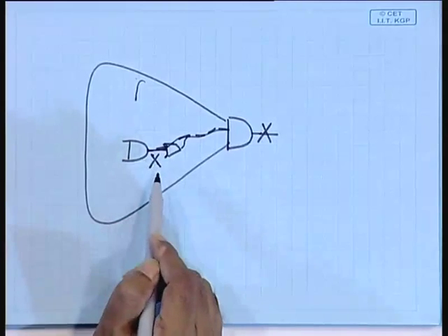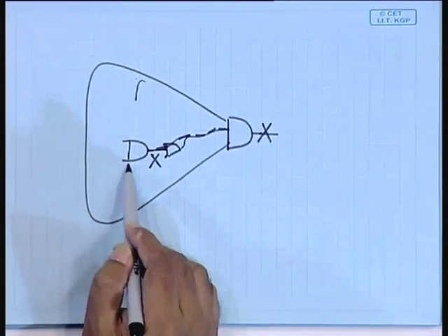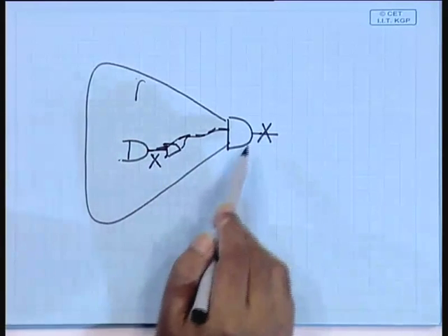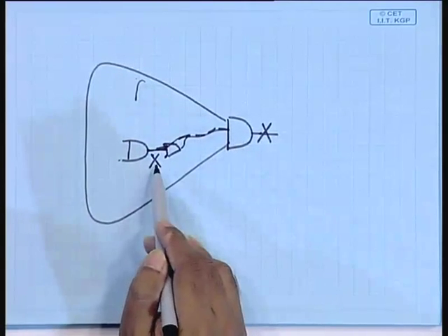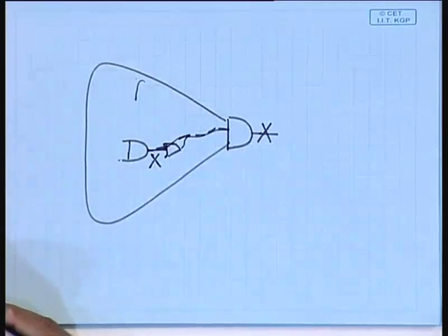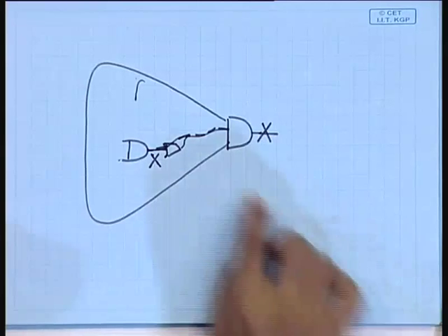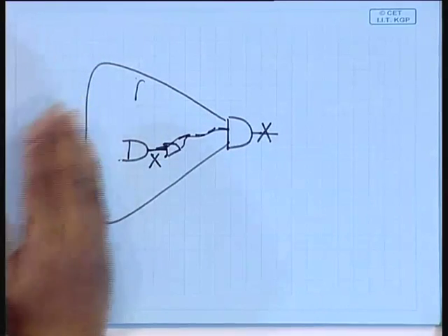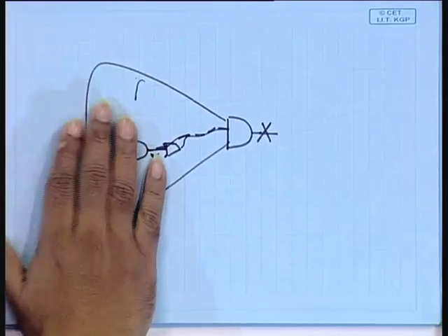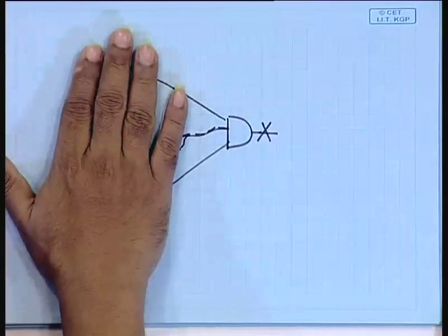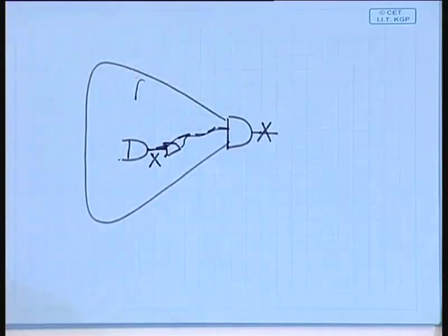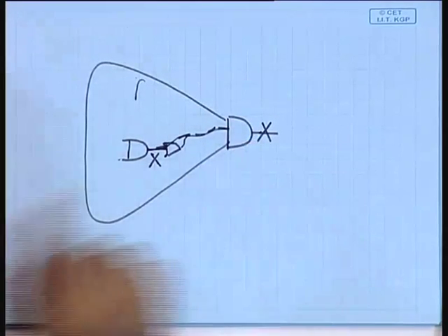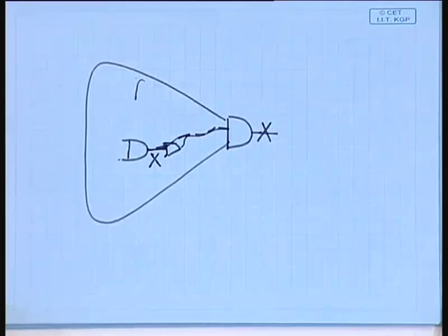So, therefore, it can never be possible that some node which is in the transitive fan in of this node gets an exit label which is smaller than the exit label of this, right. So, this establishes that when we are evaluating a particular node, if we have evaluated all the nodes which have exit labels more than this, then it has covered all the nodes that are in its transitive fan in. So, therefore, it is a good enough point of time to simulate this case. Clear?